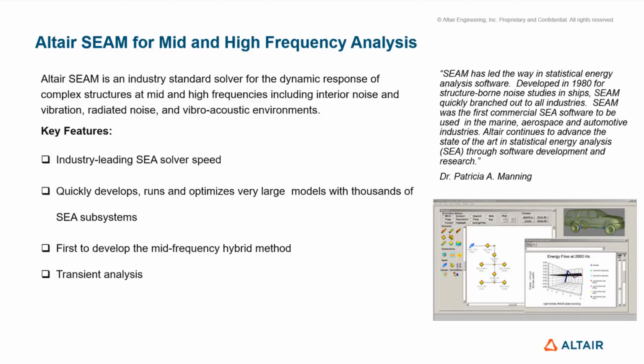So Altair SEAM is a structure standard solver for doing dynamic response analysis for both mid and high frequency analysis. It uses a statistical energy analysis solver behind the scenes to solve the problem. The entities required for it are very different from FE. So the solving time is very good, and the whole vehicle can run in less than 10 minutes if you take automotive, maybe even less than that.